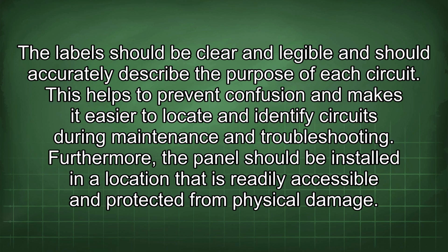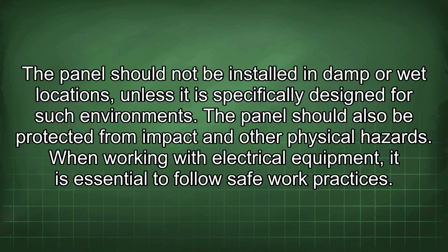Furthermore, the panel should be installed in a location that is readily accessible and protected from physical damage. The panel should not be installed in damp or wet locations unless it is specifically designed for such environments. The panel should also be protected from impact and other physical hazards.